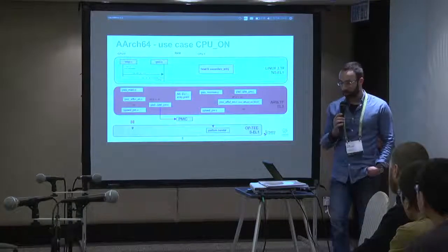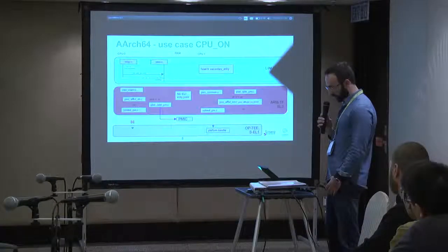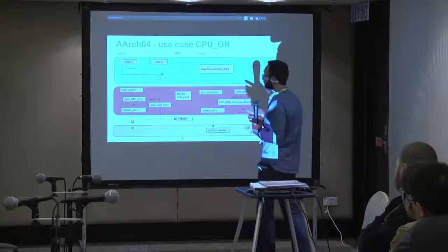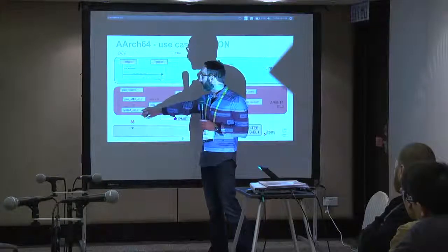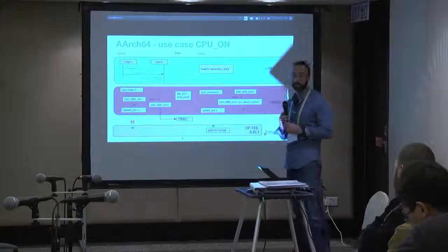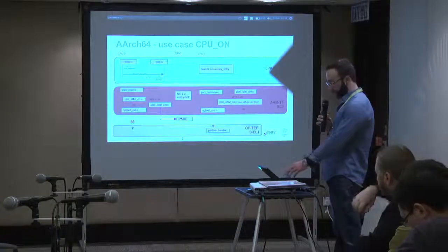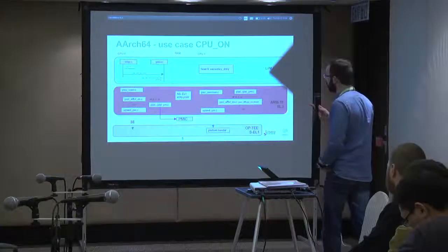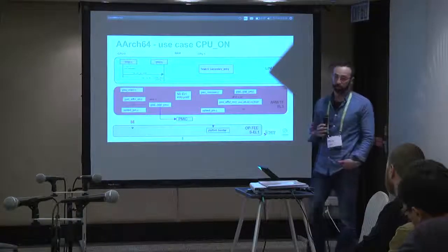In the case of a CPU on, use the standard SMP interface. The call gets handled by the SMC. After the SMC, it goes to the affinity level on. At the moment, there's no need. Actually, there's no interface to call the OP-TEE for a CPU on. The platform-specific bits will take any action required for the different affinity levels. Before, the last instruction will be to construct the PMIC to turn the CPU on.